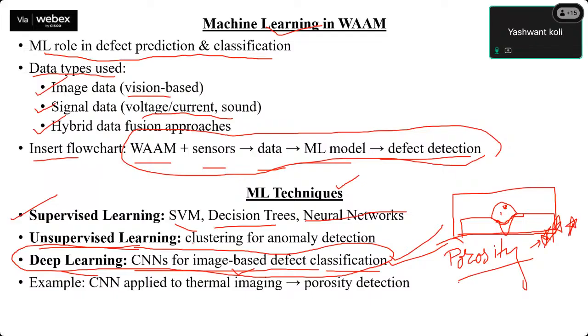And suppose we have other defects like lack of fusion, delamination, it depends on the criteria, which criteria we are following and which image based system we are following. So if we have many defects in a single image, we can classify the defects and we can sort also as per the characterized defects.